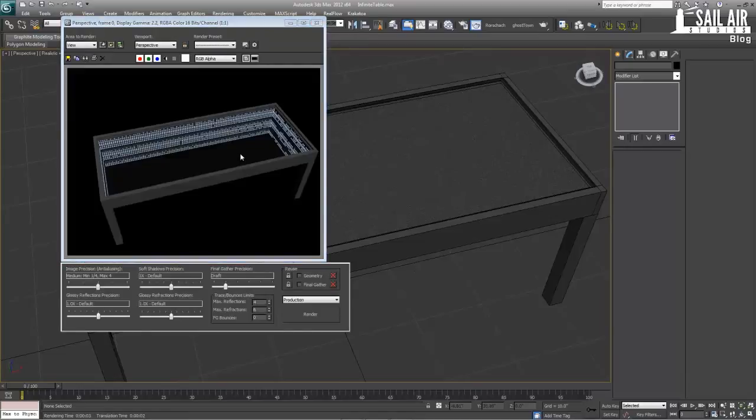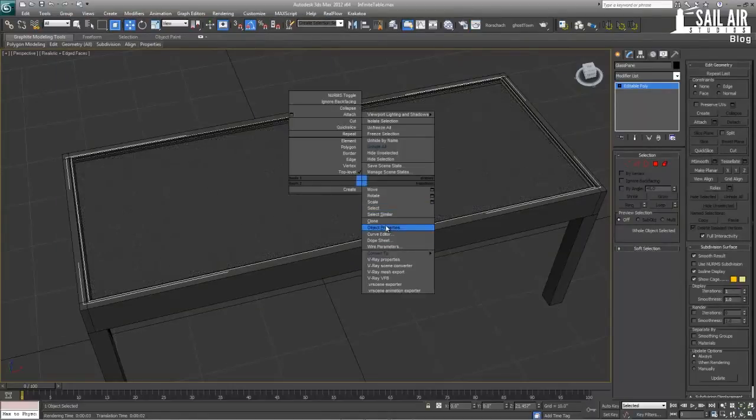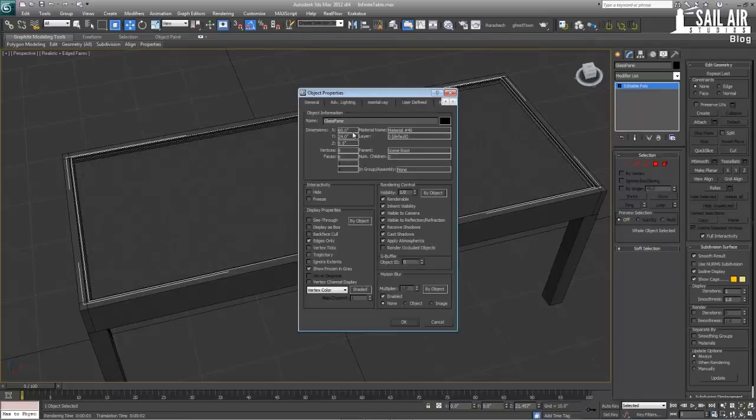Now as you can see there are a few problems. It doesn't look like all our LEDs are shining, and it only mirrors 3 times downwards. So those are 2 things that we have to fix. As well, the light doesn't look too good, and there's no real base plate, but that'll be fine. So first what we have to do is make sure that there's no shadows coming from this top thing. So right click on our top glass plane, go under Object Properties, and turn off Receive and Cast Shadows.